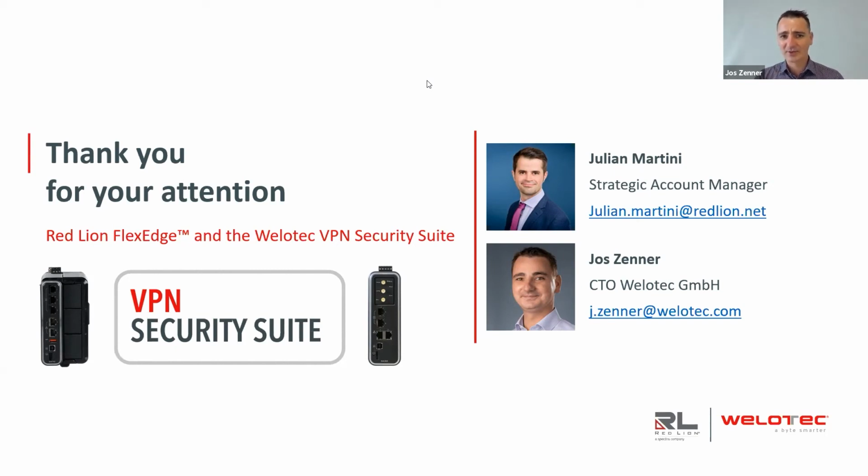And of course, you can also access them through the VPN portal. This means that in the portal, you configure one FlexEdge, and then you also configure the devices behind that FlexEdge, which means that you can access every single device behind that, for example, the HMI, the PLC, separately. And you can also manage the access separately, so that, for example, engineer 1 can only access the HMI behind one FlexEdge, and engineer 2 can only access the PLC behind one FlexEdge, and the administrator can access both.